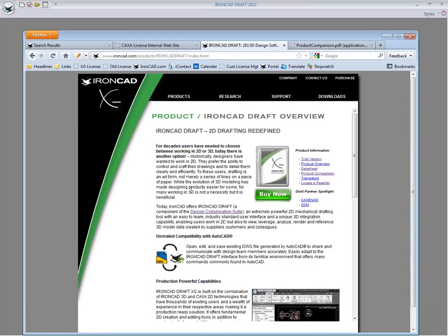And those 3D models can be from anywhere. You can import the IGES, STEP, Parasolid, ACIS. With the extra translator, you can import the CATIA, UG, ProE, SolidWorks, Inventor. Bring any of those models into what looks like a scene environment. You can move things around, but you can't change the geometry. But you can move parts within an assembly. You can use the tri-ball. And then you can start up the draft mode and make drawings. And those drawings are associative back to the model.